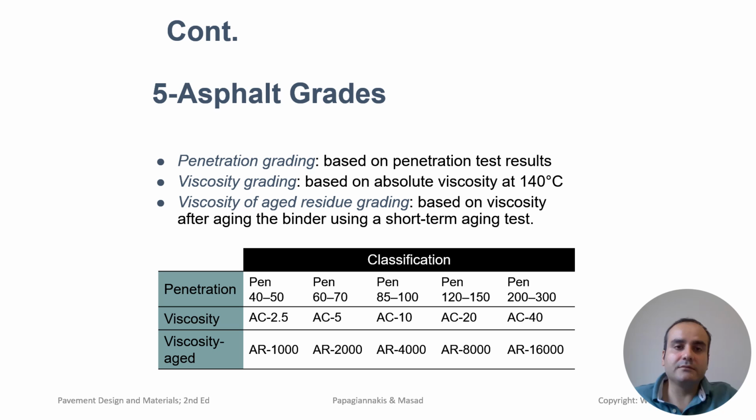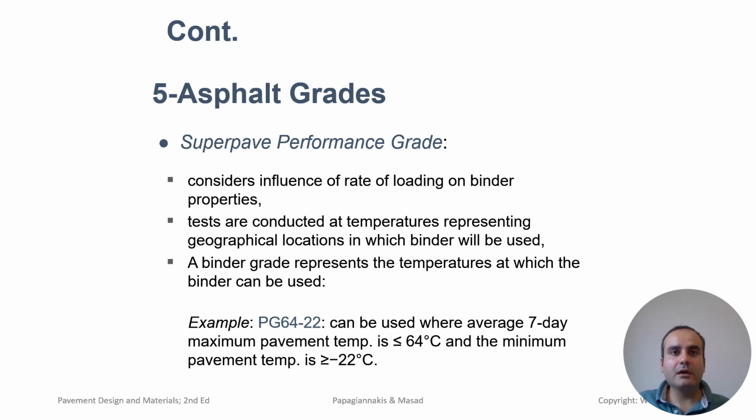The performance grading system is the most advanced and widely used system for selecting asphalt binders. This system was developed as part of the Superpave system and is based on the binder's ability to resist rutting, fatigue cracking, and low temperature cracking over a wide range of conditions.